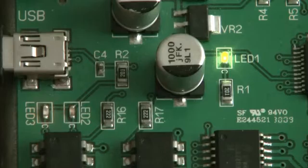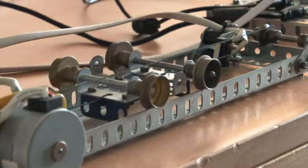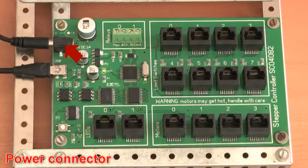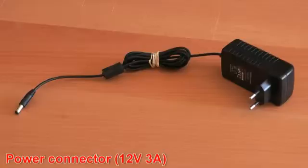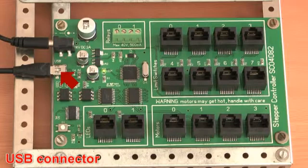The stepper board serves as the interface between your computer and your Meccano model. It accepts the requests from your computer and then translates them into action. This is the power connector of the stepper board. To power it up, you will need a 12-volt, 3 amps power supply, which you can get in any electronics supply store. Here, you will plug the USB cable that connects the stepper board to the computer.